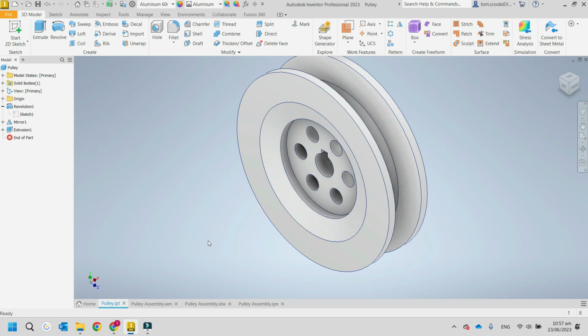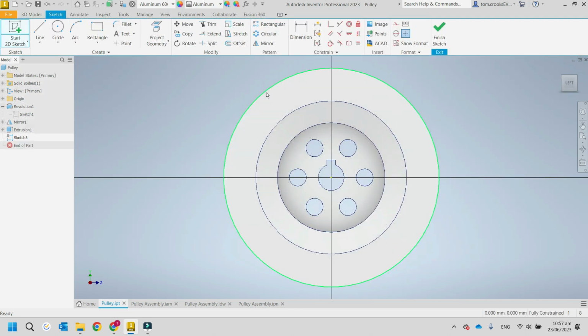That's because, say if I were to go into a sketch like this and I do a line, I see the line functions lit up, so I'll do it here. See, it's carrying on with that line, so I'm just going to go escape and that ends that command, and then say I want to do a circle and then go, oh whoops, I'll pick circle, I don't really want circle, go escape, and then I'll delete that.